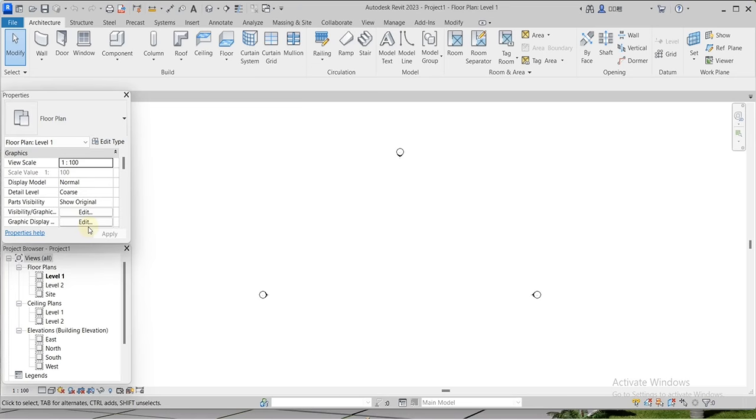Step 1. Set up the project. For the sake of Revit beginners, let's quickly set up the project. If you are used to this, please kindly skip to the next step. Let's start the right way. First, open Revit and create a new project using the architectural template. When you open it, set your units correctly because wrong units can ruin the entire project.